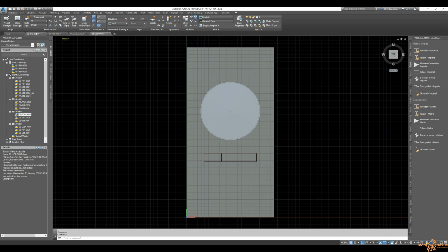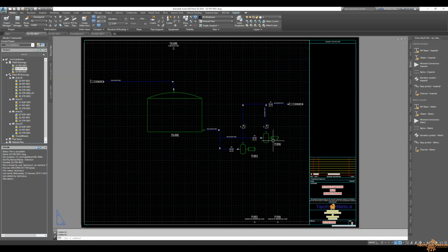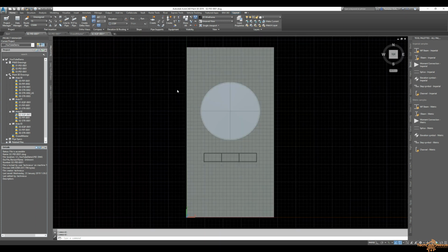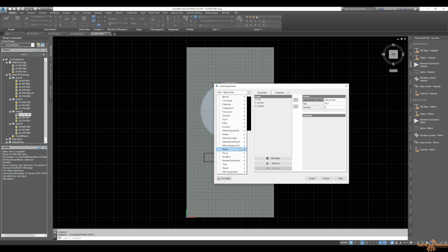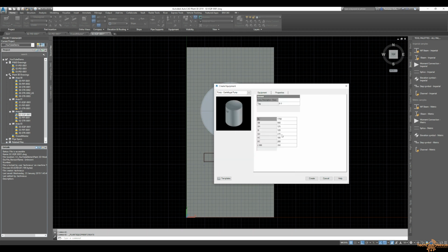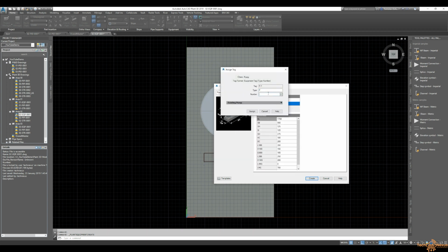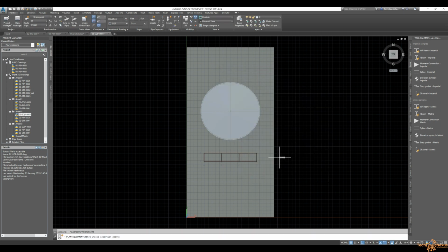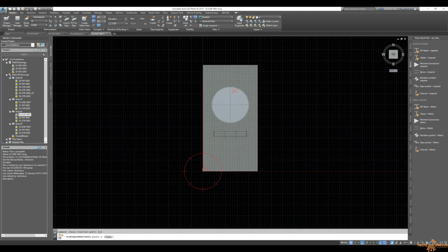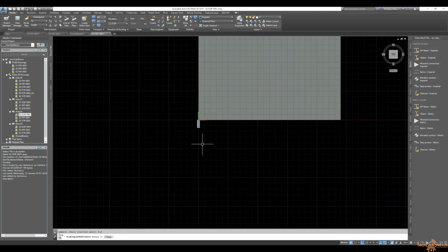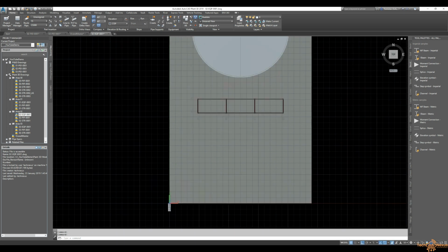So now we've also got P3 and P4. Like our other model, I'm just going to leave that as a quite generic centrifugal pump until we start getting data sheets possibly from the client. So place it at 0, 0, and it's going to be facing up the screen, up north, because it has to get its suction lines from this tank.